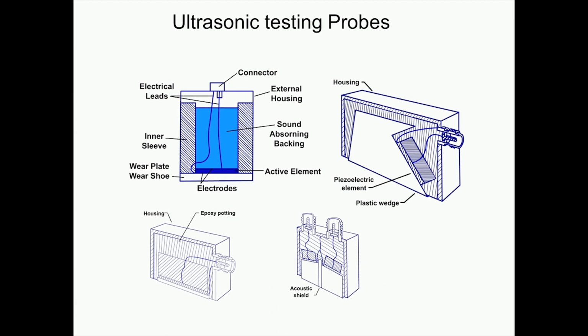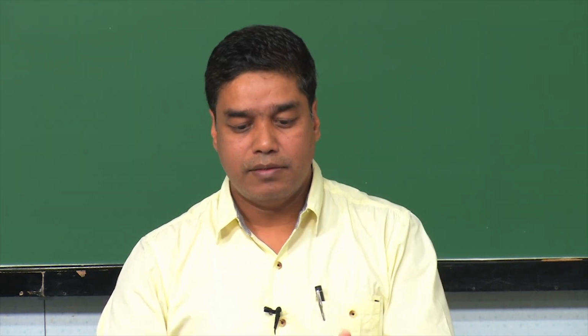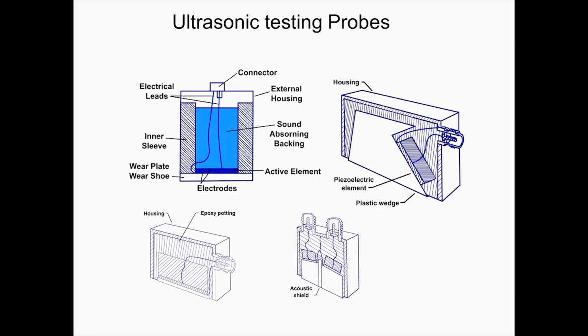And the other aspect of this is that it also comes in a particular angle. Okay. So, the ultrasonic beam can be sent normally or perpendicular to the surface, to the sample, or it can also be sent at some angle, because in many cases, as we are going to discuss later, an incidence at a particular angle is also needed, because your defects and flaws can lie in different orientations.